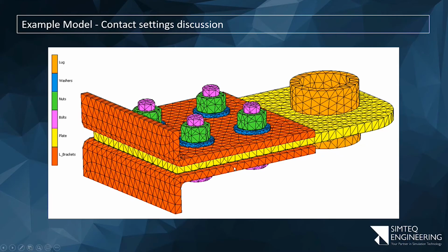So in that case, any load that you apply, this will slide around and it's going to be difficult to get a static solution. In a transient analysis, it would be easy, but not in a static one. But again, it's not physical. So that's why you'll either run friction between these parts or you'll just glue them together. To be honest, I'll think very carefully about gluing these, but over there I may still consider gluing the washers and the bolts, washer nut and the plate together. But again, you can use friction as well.